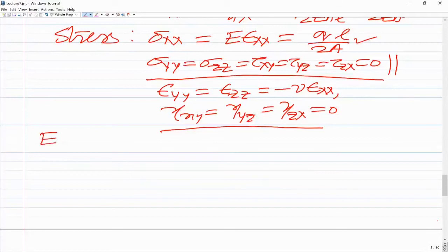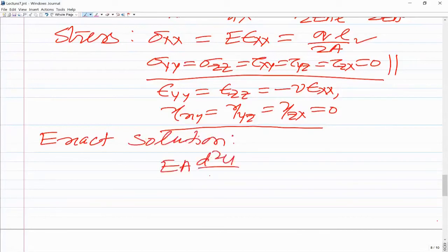But for more complex engineering problems, the analytical solutions do not exist. So we then rely on the finite element method and maybe some comparison based on strain gauge measurement and those kinds of things. But for this, at least we will have confidence in the finite element method, that yes, it gives an accurate solution compared to the exact solution wherever it exists. So for the exact solution, EA and Q are constant. So the differential equation will become simply EA d2u by dx square plus Q equal to 0.